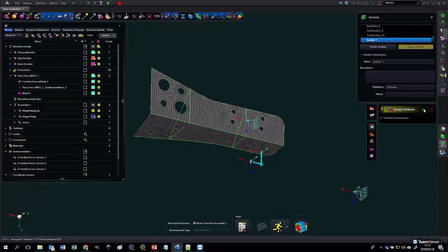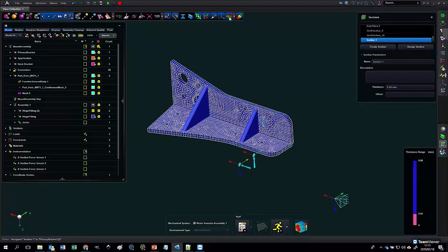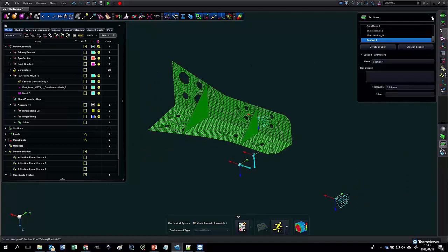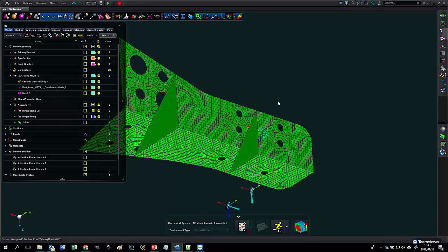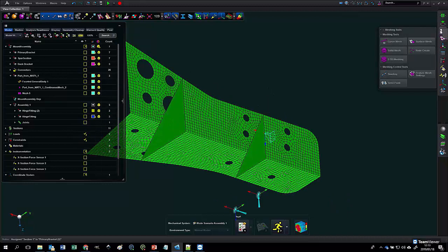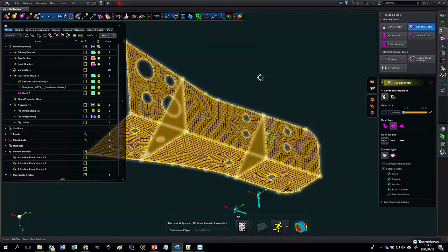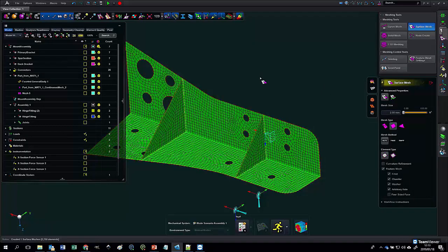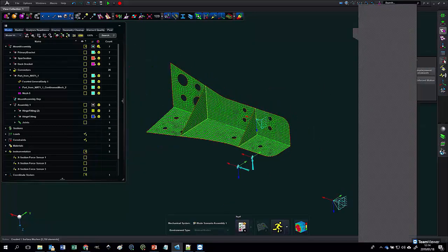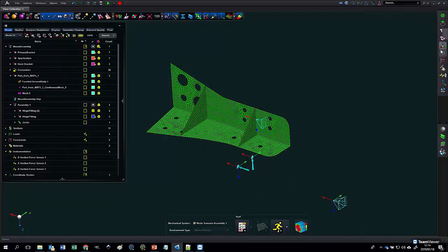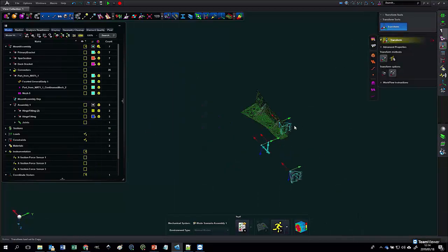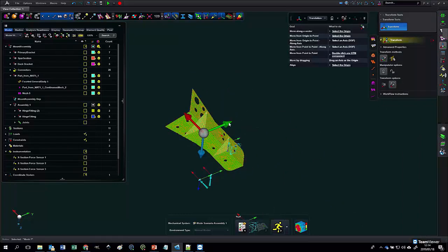Assign it to everything there. Okay, so that gives us a 5mm thickness. If we mesh those, they will obviously be meshed as part of that body. I want to make two copies of it and show you the differences between stitched meshes.